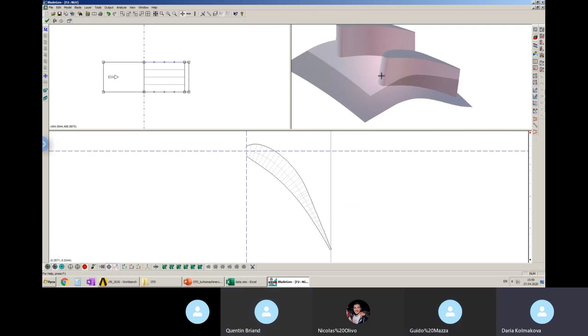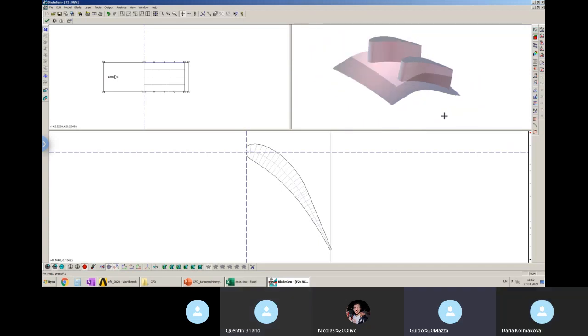So speaking about the twisting of the blades, now you can see that this blade is rather straight along the height. And do not forget to perform this part 2, stack blade on centroid. And I think for the nozzle guide vane, that's all.